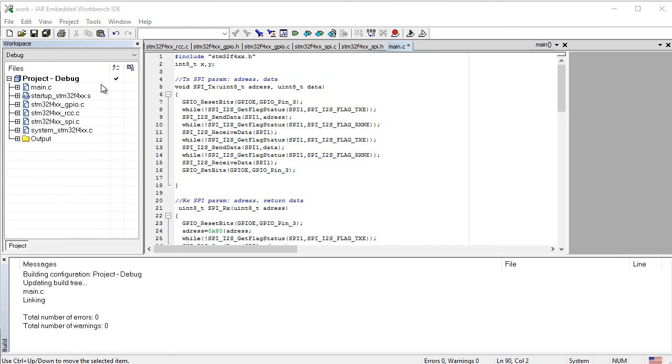As an exercise, you may try to modify it by activating the interrupts to spare a couple of microseconds wasted in polling, following the examples given in my previous tutorials.